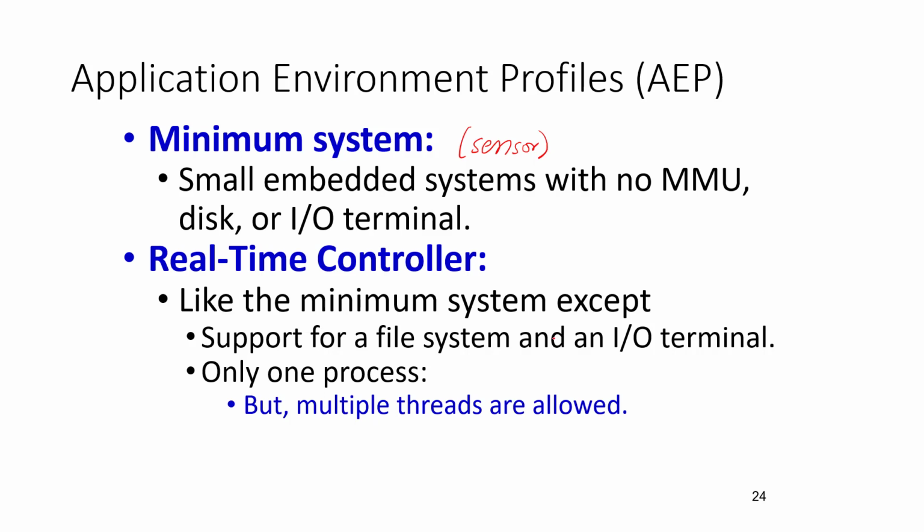Then we have, you know, it still supports a single processor. This is a limitation: a real-time controller will still simulate a single process. The way that you would simulate multiple processes via a single process is that you will basically call multiple functions. Here, this aspect also has been discussed: how do we support that many processes? We don't support that many processes, but we simulate something to ensure that it is calling one function, and this function, think of it as a process. It returns, then we call the next, and so on.